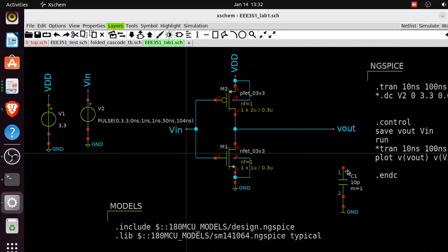So what does this mean? It means if this is the load you want the inverter to drive, the load would affect the inverter's performance big time. Maybe what this capacitor is doing is shorting, because with changing voltages with frequency, a capacitor becomes a wire.